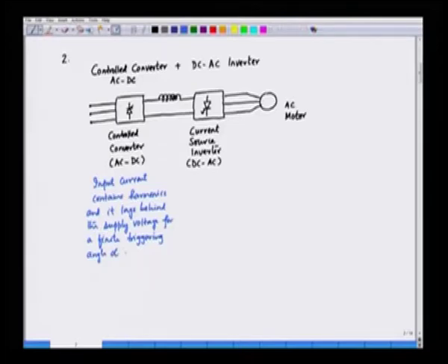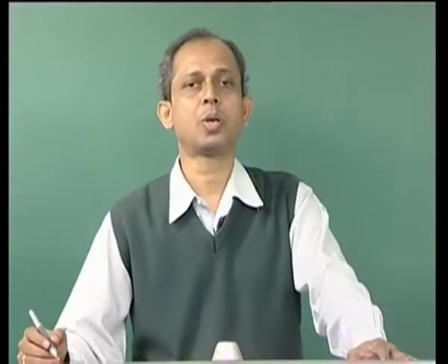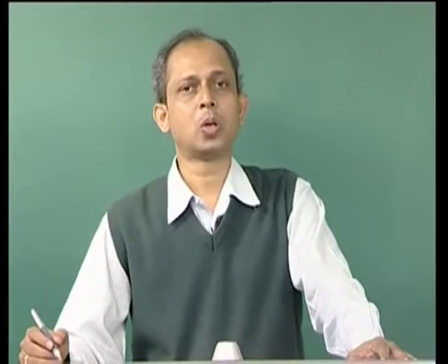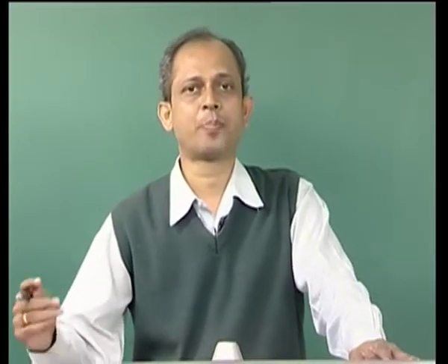So, this kind of topology where we have a current source inverter feeding an AC motor is also not utility friendly. Although we are able to control the motor, we are not able to have a system where the power system is going to be more free from harmonics. The power system in this case will contain harmonics, and harmonics will bring down the power quality.